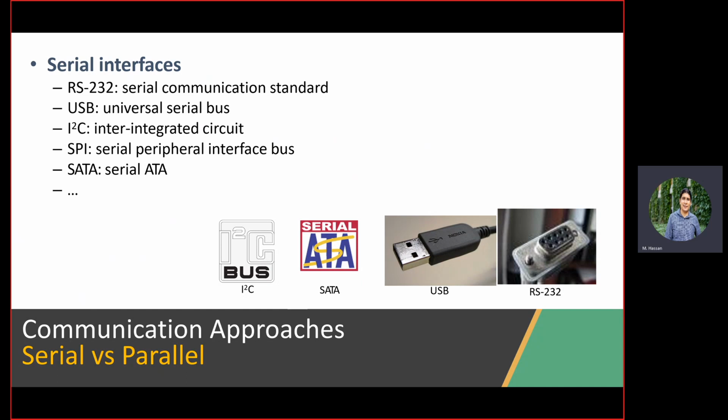Okay, good. So this is basically the RS-232. That's the parent or the father of all the serial protocols, right? You don't see it nowadays because USB is just the winning approach right now. But all of the protocols that came afterwards, especially USB, are in fact building on top of the technology of RS-232. For those that are hobbyists of electronics, you will find a lot of circuits that do the translation between RS-232 and USB or RS-232 and UART as well. You can interact with an RS-232 chip through UART. I2C and SPI we will deal with the most, so we'll cover those.